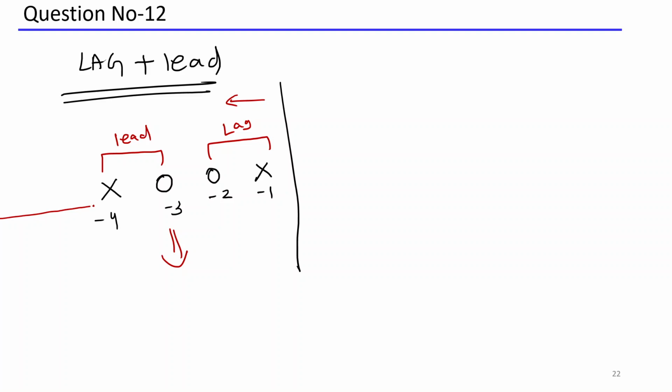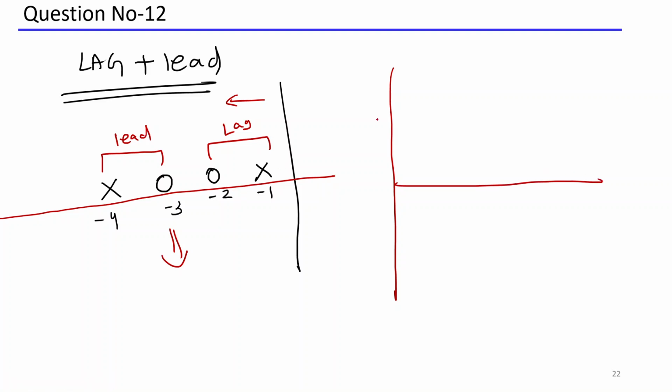So you have a pole at the origin. First you have to draw the magnitude plot like that. So you are encountering a pole. Let's say you are starting with 0 decibel. Next, the slope is 0 decibel. Then you are encountering a pole, which brings -20.